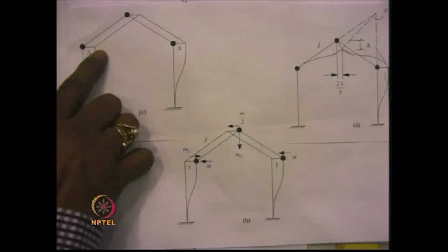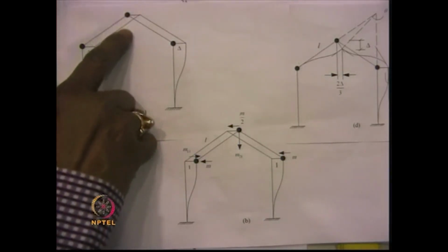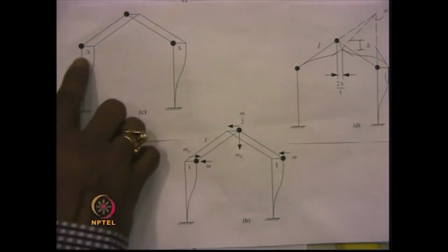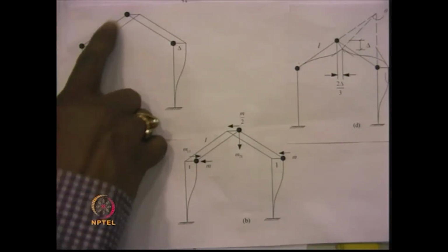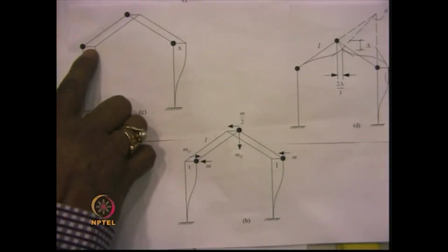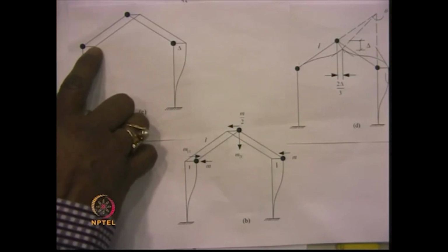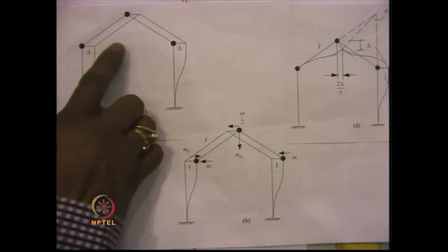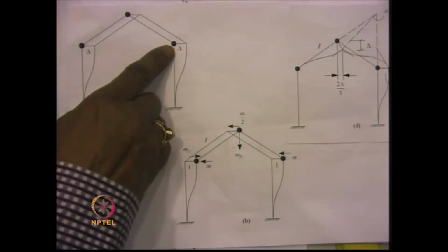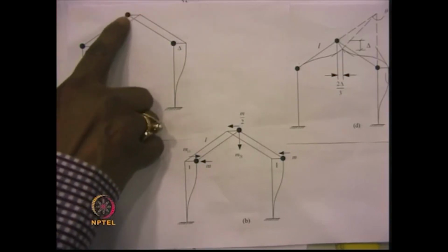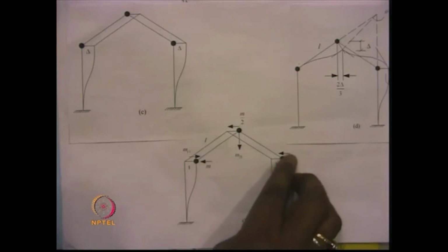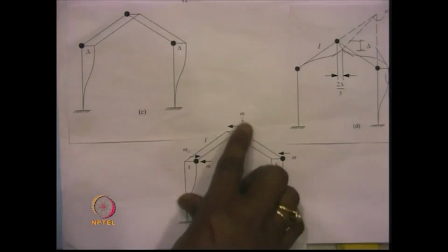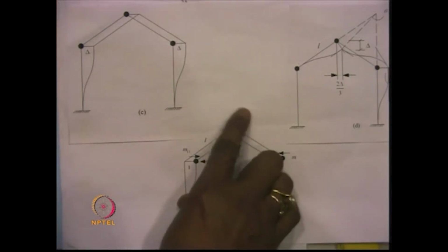That is the case where we have a translational degree of freedom defined here and a vertical degree of freedom defined at the crown. For that we give a displacement to this particular degree of freedom, locking this one, and the displacement is given such that unit acceleration is produced at this point, and unit acceleration will also be produced at this point, and also at this point. As a result, the inertia forces developed here will be equal to m into 1, here it will be m into 1, and at the crown the inertia force developed is equal to m by 2.